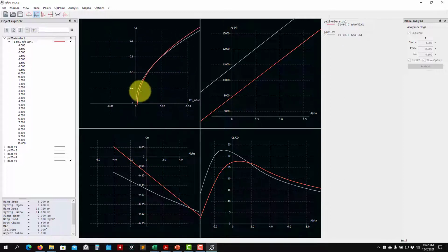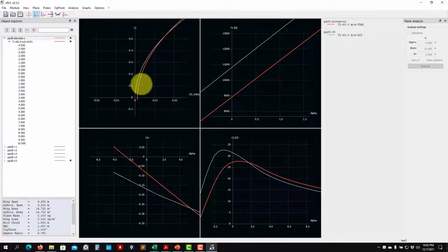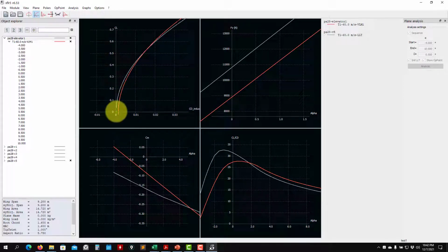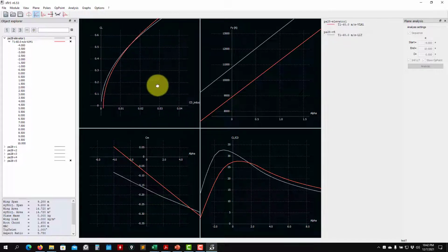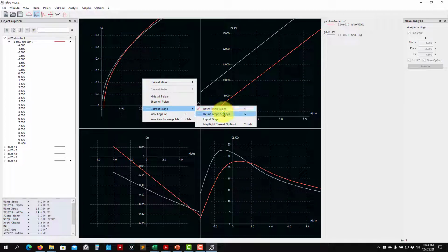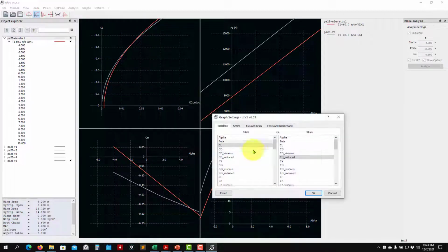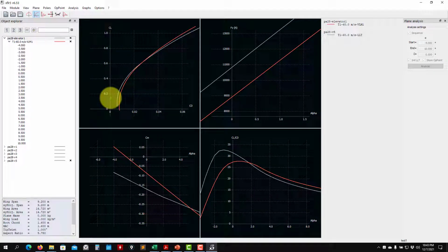Also look at that. By trimming the airplane, we're also increasing the drag. So see that the fact that you need to trim increases the drag, and this is just induced drag. So if we look at the total drag, you have it there. The fact that you trim, you add that surface, you are adding more induced drag. You are also adding more viscous drag. But see also a nice behavior here, that you have it in kind of the same condition. And also we can plot this.